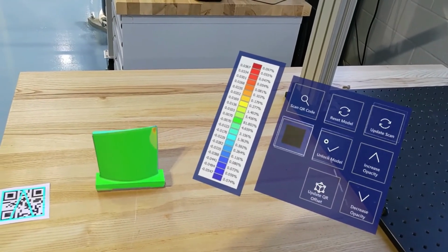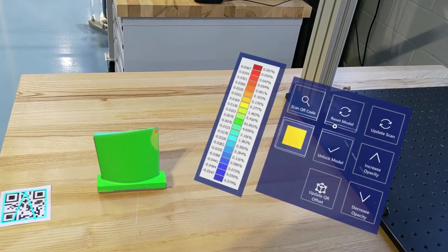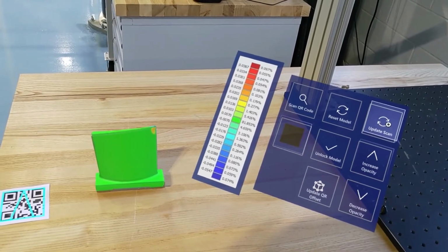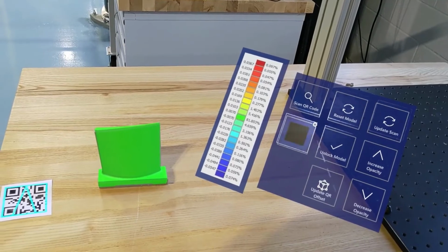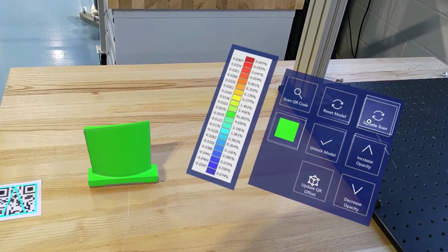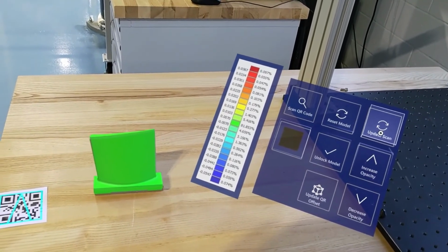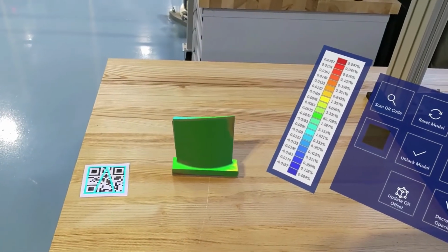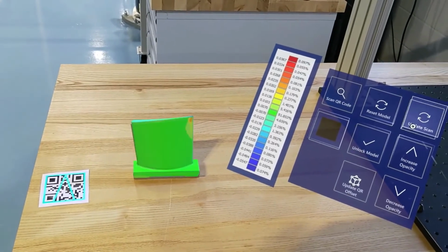You can see as they go through and update the scan, that top right corner had a very high point that is slowly being sanded down. And you can see that the model is slowly becoming more green as updated scans are coming in. This is useful as a visualization process because it allows you to see things that might not be super clear when you're just looking at it with your eyes. You're getting an actual deviation map and measurements of what's expected versus what the actual piece is showing as far as the deformations.